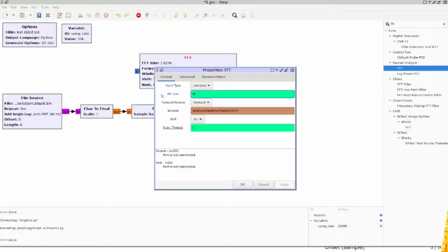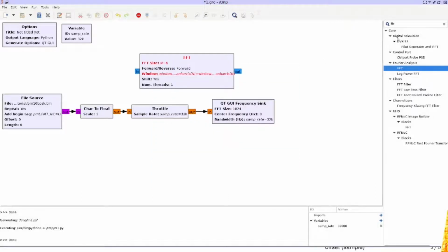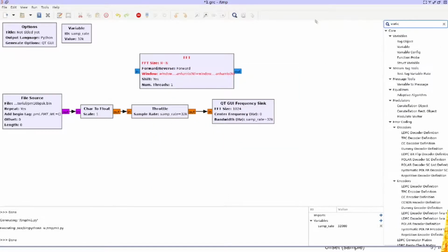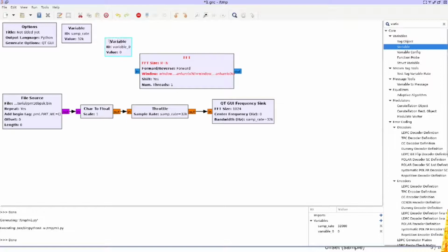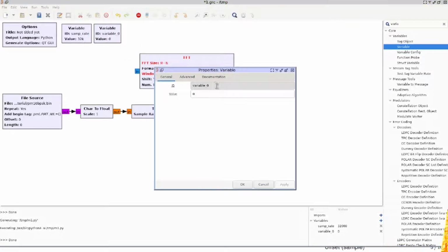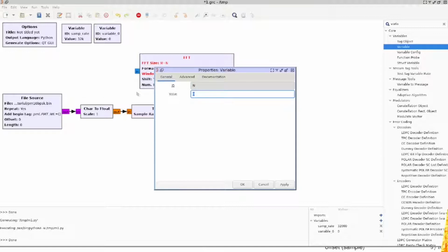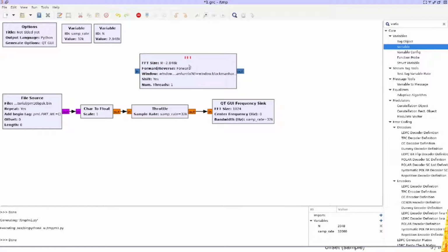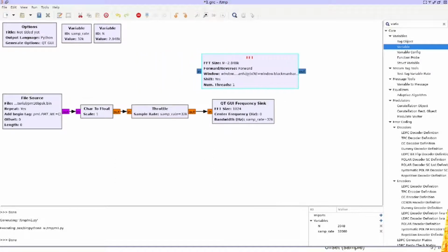Actually, we need to accumulate enough data that we are going to calculate this Fourier transform. So let's say we want n elements, and we're going to have some windowing, so we have the same n, and I like to create a variable holding this n quantity here so that we can easily change the Fourier transform size. So say we have a 2048 element Fourier transform.